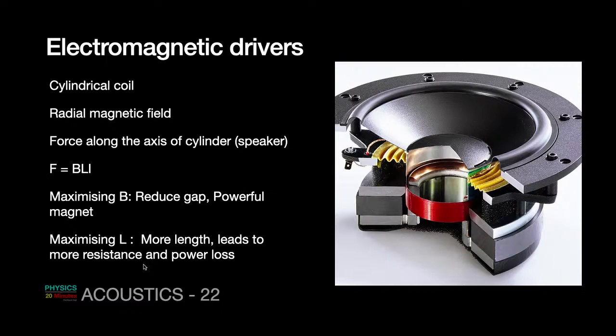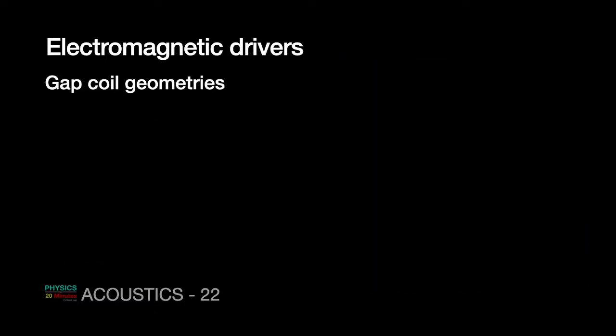So do remember that whenever one designs a speaker, these are the two driving conditions. One, the force should be maximized because that gives you the highest efficiency. For that, B and L should be large. And the other is high fidelity, which we are going to talk about mostly in the next class.